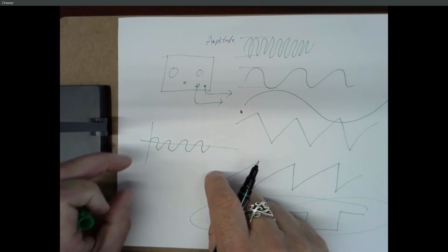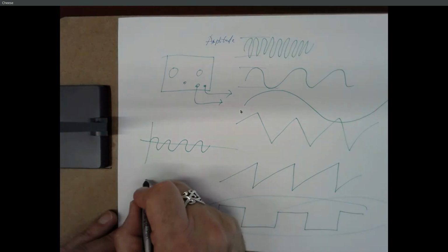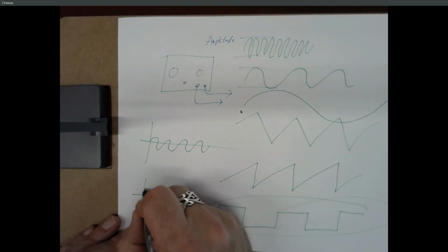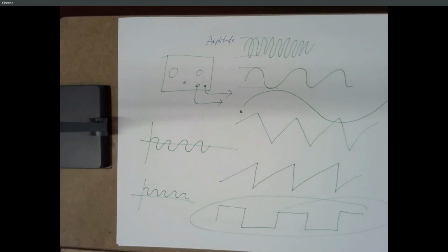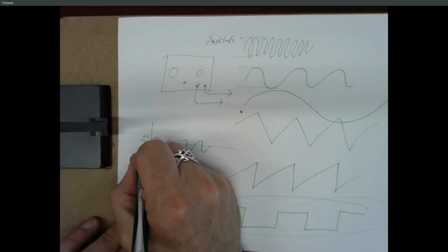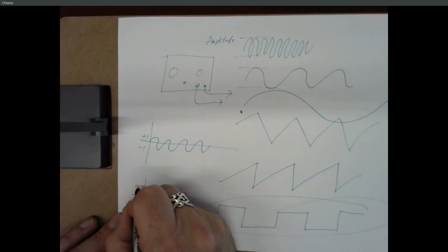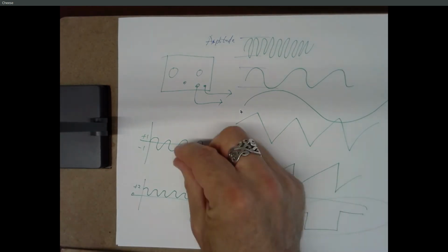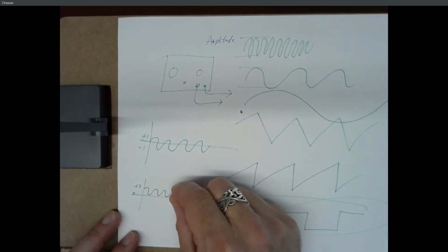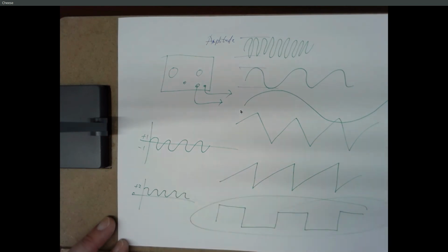Right, certain frequency, certain amplitude, exactly the same frequency, exactly the same amplitude. But this goes, say, from positive 1 volt to negative 1 volt. This goes from positive 2 volts to 0 volts. So it's been shifted up a little bit. Okay, that's what we call a DC bias or a DC offset. But I don't think it's adjustable on your function generators.